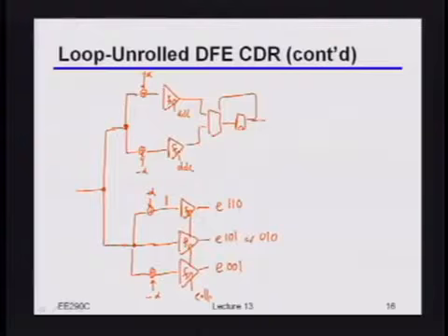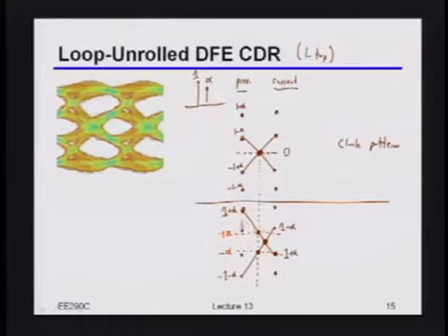But to do it live, I think has similar problems as what the normal loop unrolled DFE has, in the sense that there's really no analog level that you're looking for that gives you exactly that information. To be fair, the only saving grace here is that you really could look for this point in time here, but that would assume that you locked in the right place in the first place. I'm not exactly sure how you would check that you're really in the same time when you're doing the estimates this way versus that way.